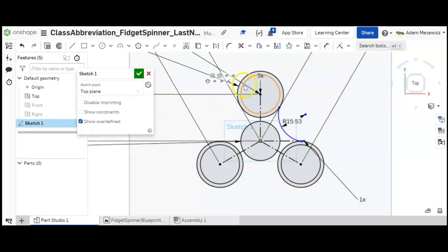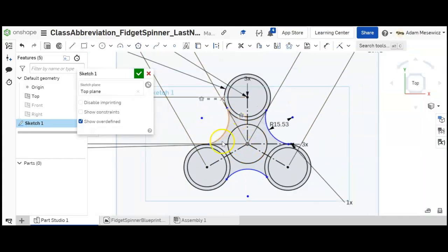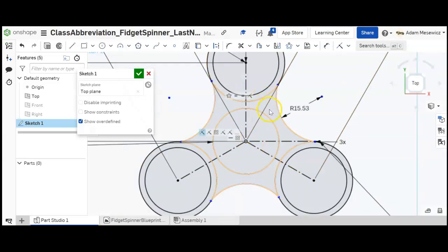of those. So you could use the arc tool again, but that would be kind of like doing too much, because you already know that this circular pattern tool can do that for you, and it can do it perfectly spaced out. So if we do our circular pattern, but this time we choose the arc, look what it does. 1, so the one that we already have, 2, and then 3, and it's exactly where we want them to be. So save yourself some time, use the pattern tool, and boom,